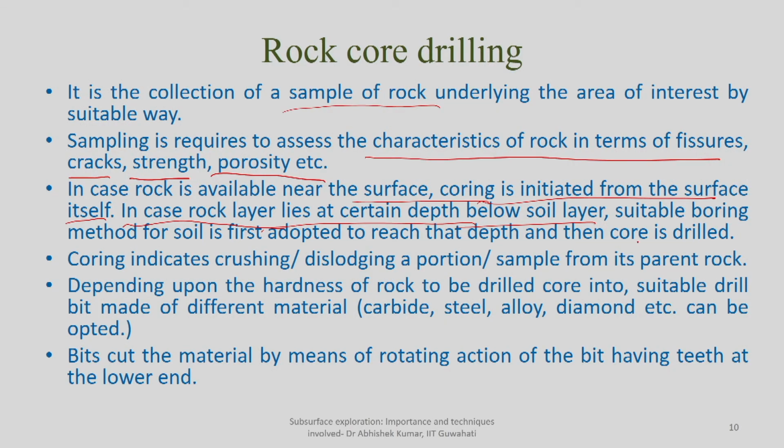If you remember, when we were discussing different kinds of auger, there was a rock catcher. You can use it if it is some local gravel kind of thing, but if it is a continuously rocky medium, then you have to collect the rock sample, which is not possible by means of that catcher. So you have to go for a suitable boring method for initial soil collection or advancing the borehole. Once you reach the layer of rock, then you start collecting the core of that particular rock.